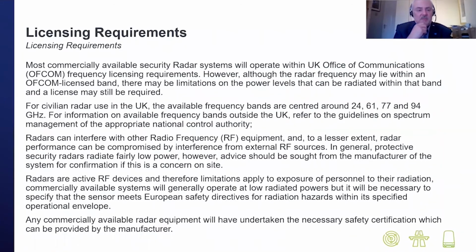Okay, so some licensing requirements as well. This also needs to be taken into account. Most commercially available security systems that will operate, particularly in the UK, must operate within the UK Office of Communications, or Ofcom, frequency licensing requirements. Even though that radar frequency might lie within a license band, there may also be some limitations on the power levels that can be used within that band, and it may still be necessary to get a license, even though it's potentially a license-free area.